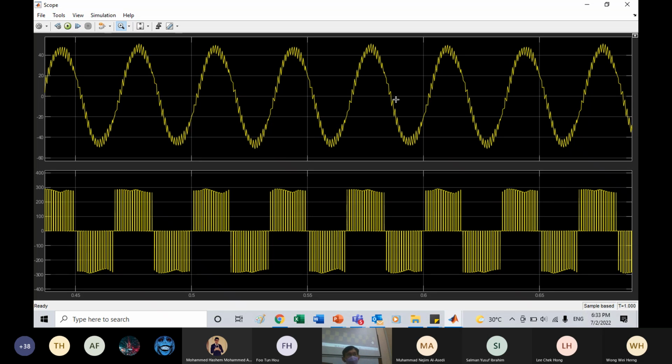So when you design a variable speed drive, a grid converter, or an off-grid converter, in the next class I'm going to teach you how to design an off-grid converter with both voltage and current in sine wave. For a variable speed drive, the voltage is still SPWM, but the current on this side, that's why you cannot use this to power up your off-grid device. It is only for motors, because it requires the motor inductance to produce a sine wave. So we will move one level up for off-grid application in the next class, and so forth.